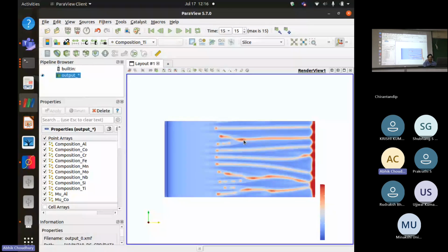What is that? Like kind of droplets? Yes, those will appear. That typically happens in solidification. These are essentially films of liquid that get broken down into small droplets. In 2D they happen due to just a breakup, but in 3D it happens due to Rayleigh instability. No, because it's solidifying, right? Finally, you will have the entire thing solidifying, but the solid fraction is reducing as the temperature field is evolving. So this is the last liquid, whose melting point is slightly different from the far-field liquid because of the segregation.